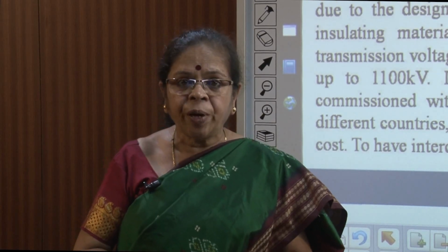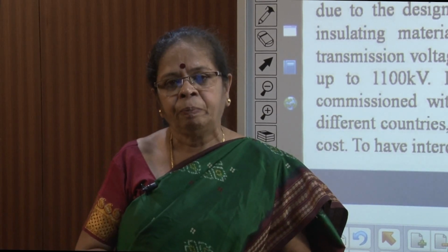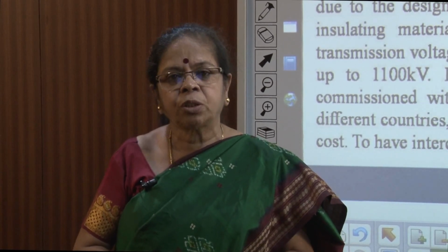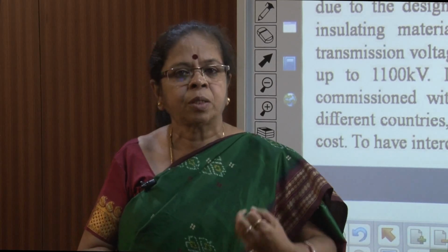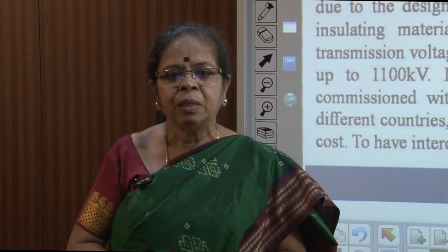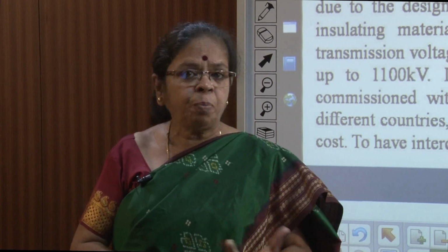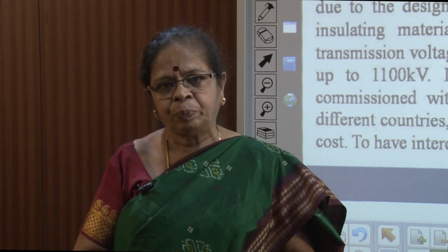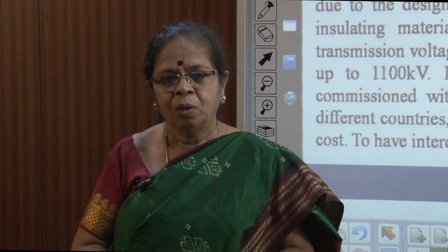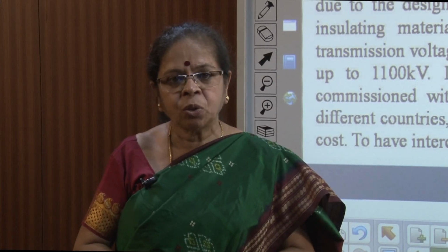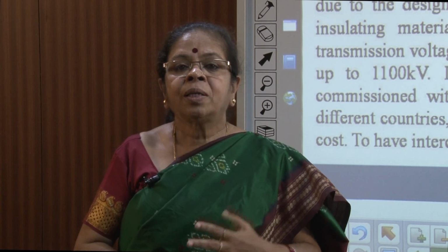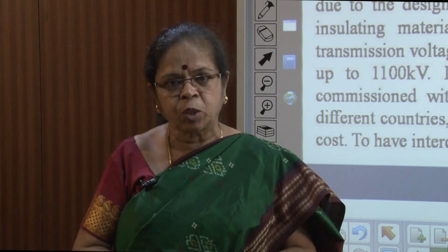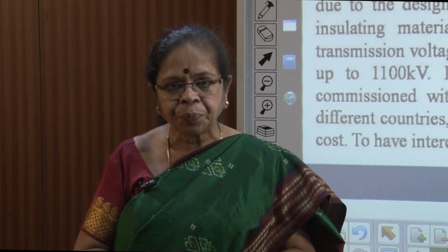And in terms of generators, I told you by this time there was a lot of work done on the invention of AC motors, single phase, polyphase, AC generators, and these were much cheaper than the DC counterparts. You do not have the problem of commutation, okay? Brushes wearing out and so on. So, the AC generator technology was another driving force for AC transmission systems to replace DC.